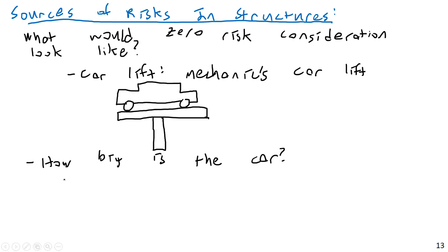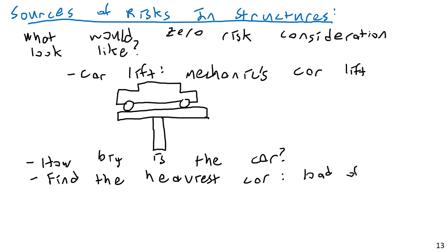I find the weight of a big pickup truck, maybe the largest pickup truck. Literally, I just go to the mechanic and ask, what is the biggest car, or the heaviest car, you've worked on in the last year? And I design the whole thing based upon that. So I find the heaviest car, and the load of that becomes my point load P.